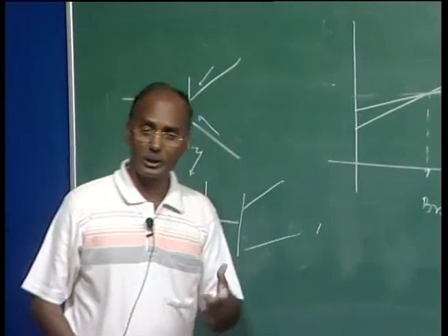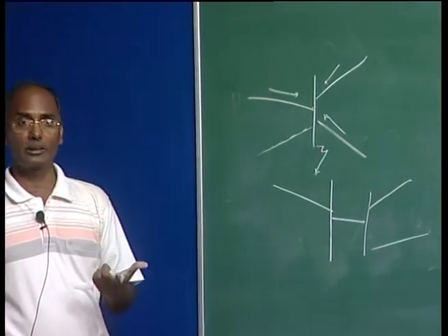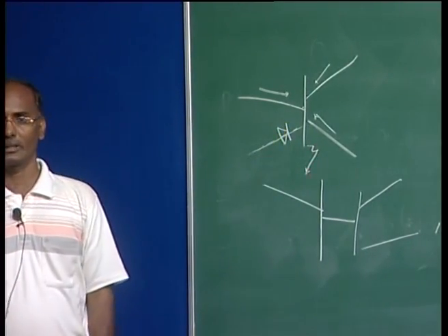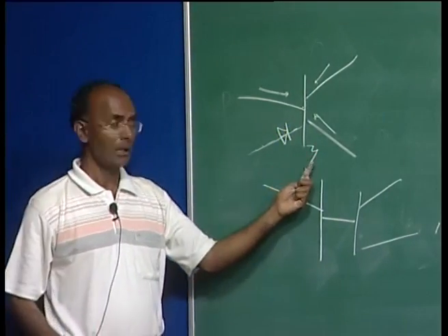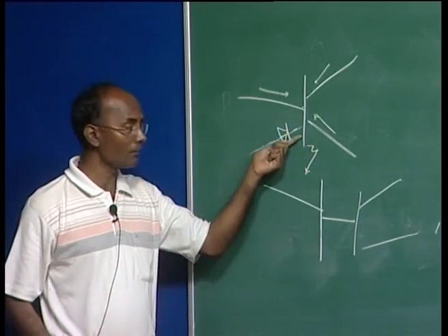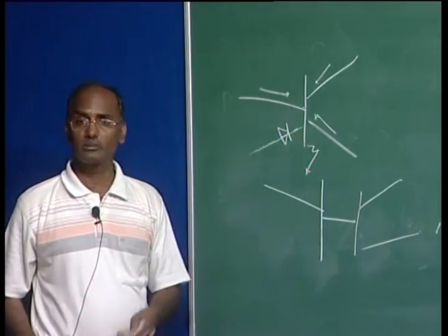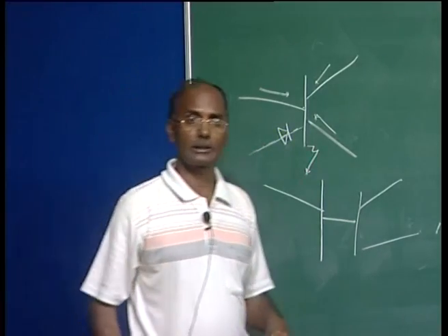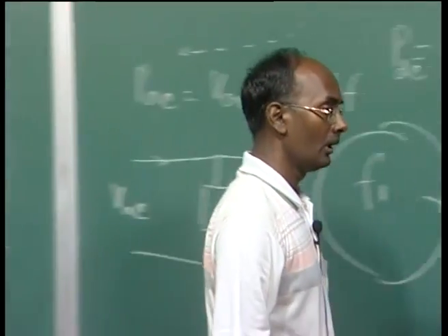But now, how is it advantageous if you have the DC system? Let us suppose I want to connect a DC system here instead of an AC system. What happens if the fault occurs? This will not contribute any fault, because the control is very fast, so no current will be contributed by it. It just blocks the fault current from this line, and this is one of the advantages of the HVDC system as well. That is why it is written no transmission of the short circuit power from another side onto that bus. So, it is advantageous in that case also.